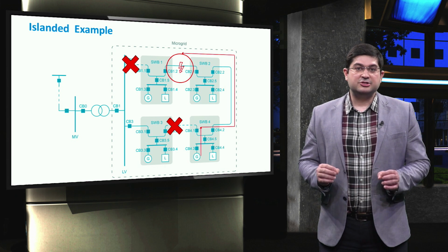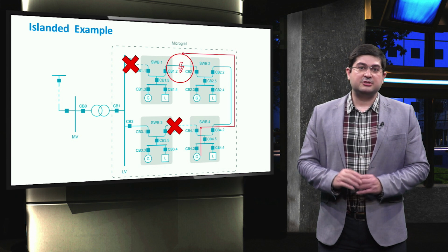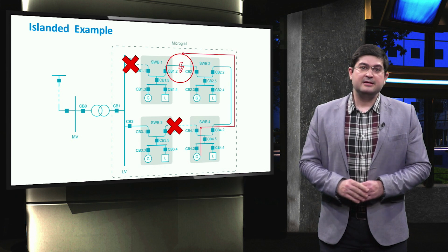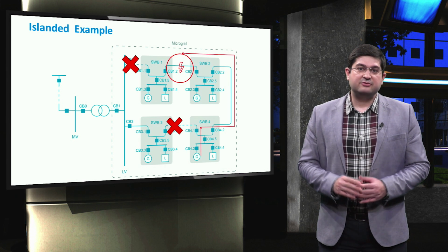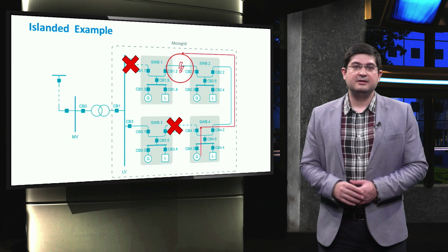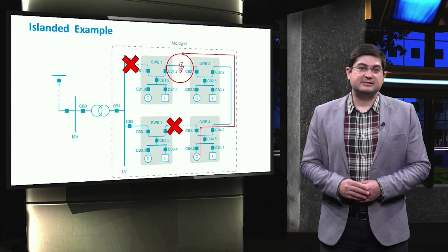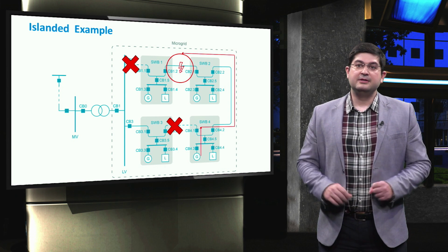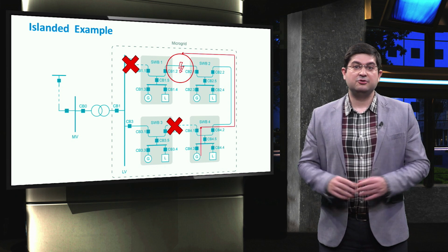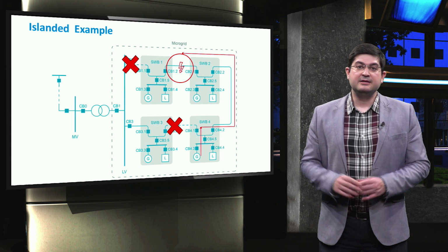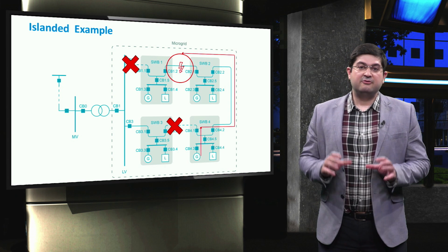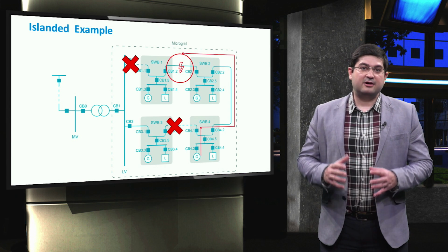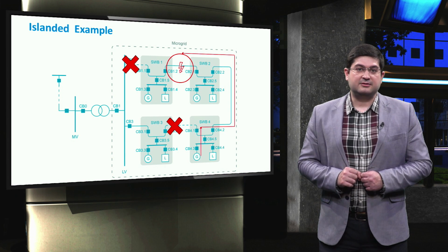Moreover, the point of the connection type and power production of the electrical components largely vary during the operating of microgrids over time. These frequent changes in the mentioned factors may require continually adapting the protection according to the new operating states of the microgrid. Therefore, the adaptive protection is implemented to ensure the accurate performance of the protection during all the operating conditions of microgrids. In this video, we analyze the case that one microgrid becomes islanded from the external grid, while its protection settings remain unchanged according to the ones of the grid-connected mode.